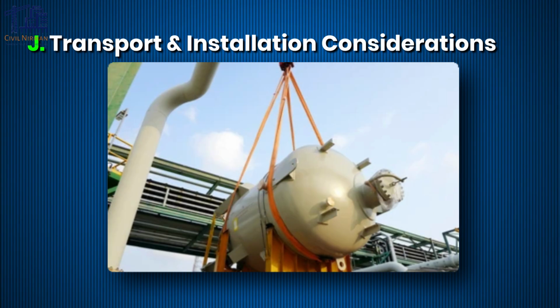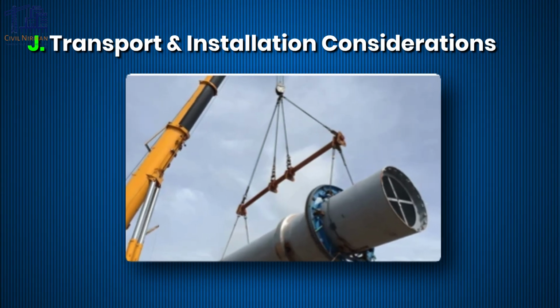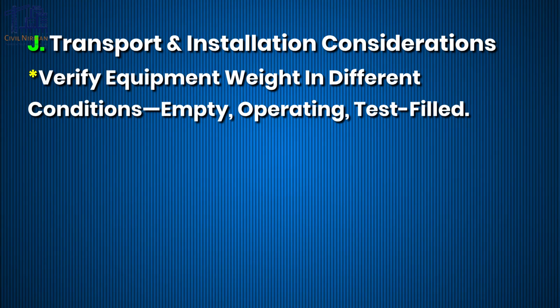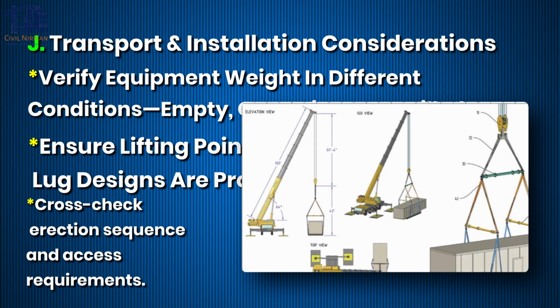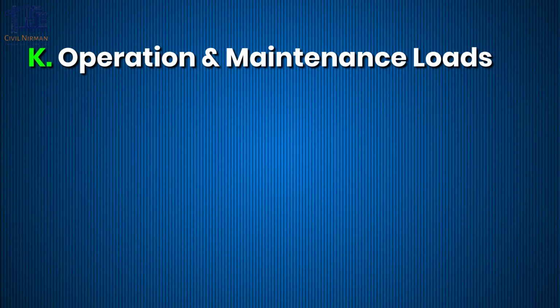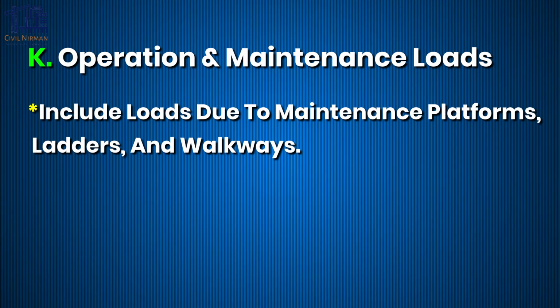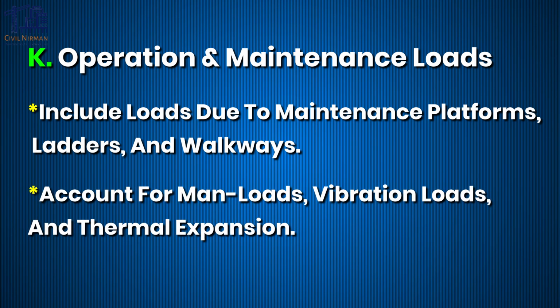Next important part is transportation and lifting consideration. Verify equipment weight in different conditions like empty, operating, test and field condition. Ensure that lifting points and lug designs are provided. In that as well, cross-check the erection sequence and access requirements. Next important point is operation and maintenance loads. While designing, include loads due to maintenance platforms, ladders and walkways. Account for man loads, vibration loads and thermal expansion.